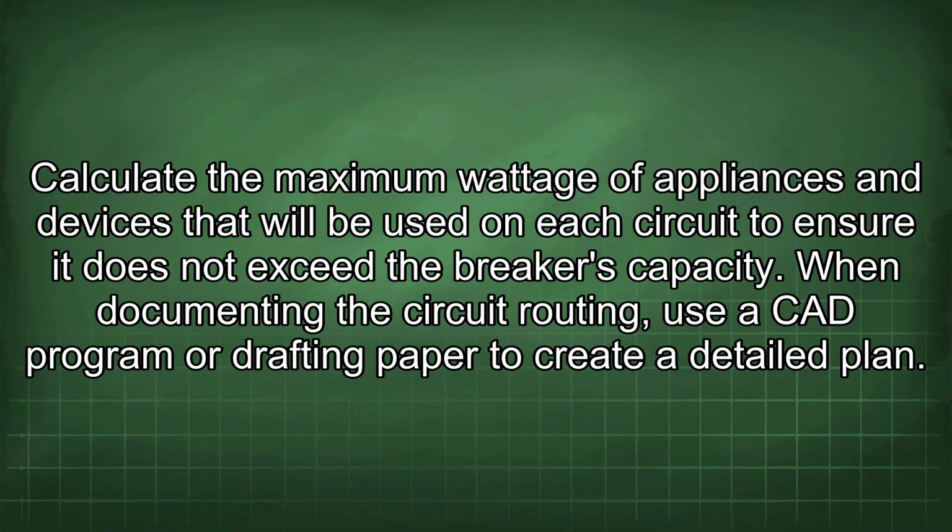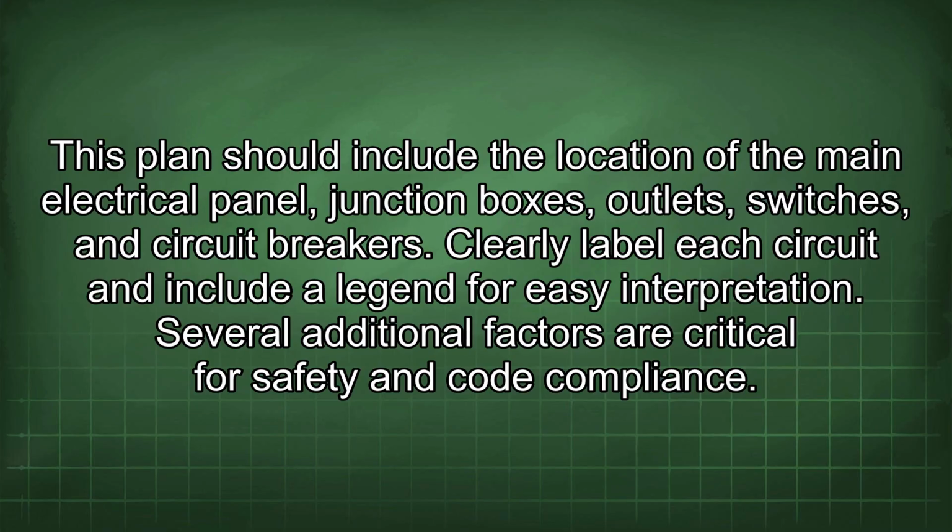exceed the breaker's capacity. When documenting the circuit routing, use a CAD program or drafting paper to create a detailed plan. This plan should include the location of the main electrical panel, junction boxes, outlets, switches, and circuit breakers. Clearly label each circuit and include a legend for easy interpretation.